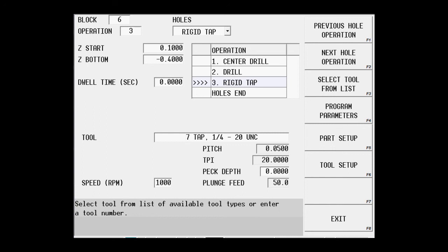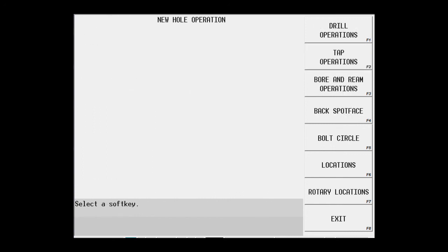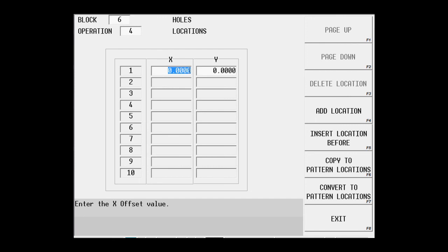Looks like our first hole is located at 1.775 in X and 3.95 in Y. We're 1.95 over from the first hole, so 1.95 plus gives me my X. And I'm going to keep this Y as my location for the next hole, which would give me my bottom 2 in this case. Now, from the original hole, I don't need to change. I'm moving up to the upper right now, and I'll take that 1.95 minus,